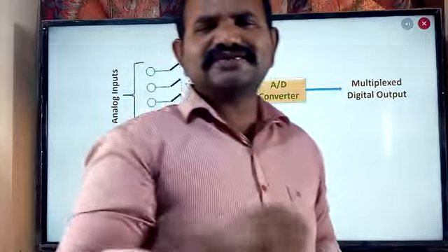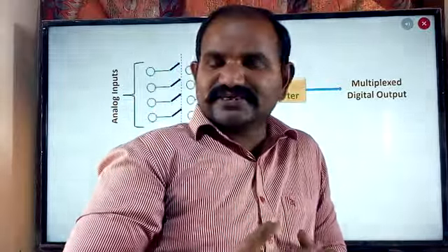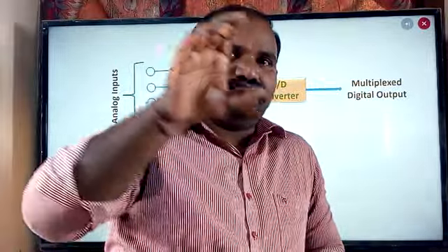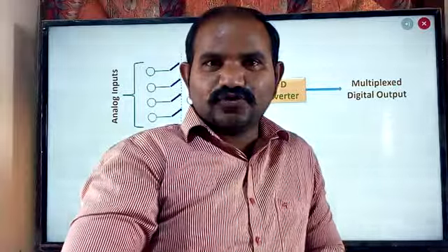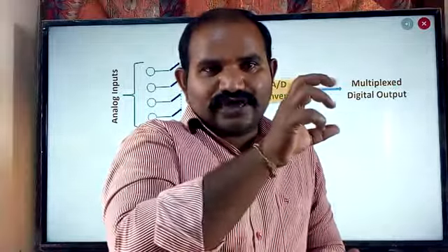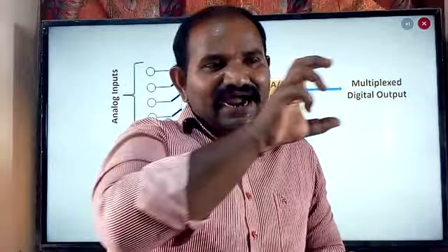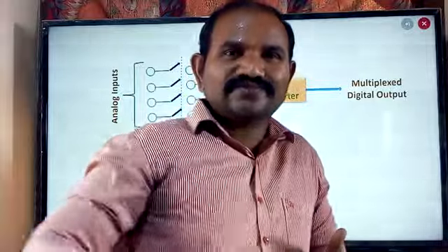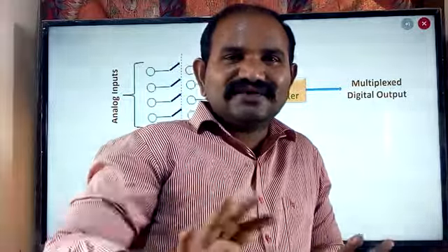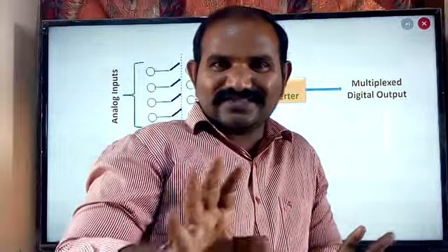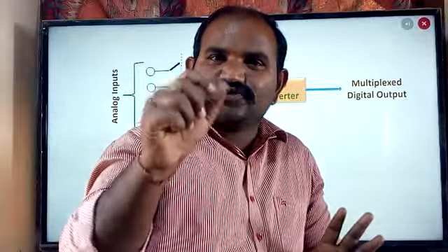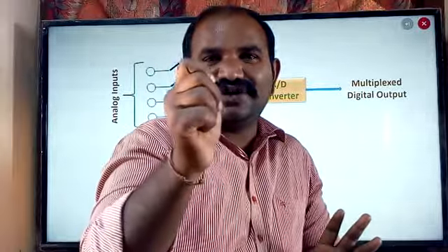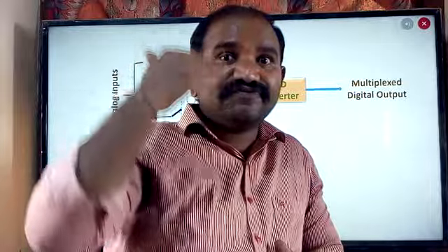One of the best examples is the information in the city buses, where we are using matrix displays. It shows some bus number, route number. Let us suppose I am using the 218D, which is a Dilshad Nagar bus. When we are using the 218D and it is printing on the display and keeps on moving, at that time all of us think that the LEDs are glowing and it's moving. Actually, all the LEDs are not glowing at a time. We can't see that one. Actually, only one row of LEDs is going to blink at a time, but that duration is only in the microseconds range, so that we can't observe it with our naked eye.